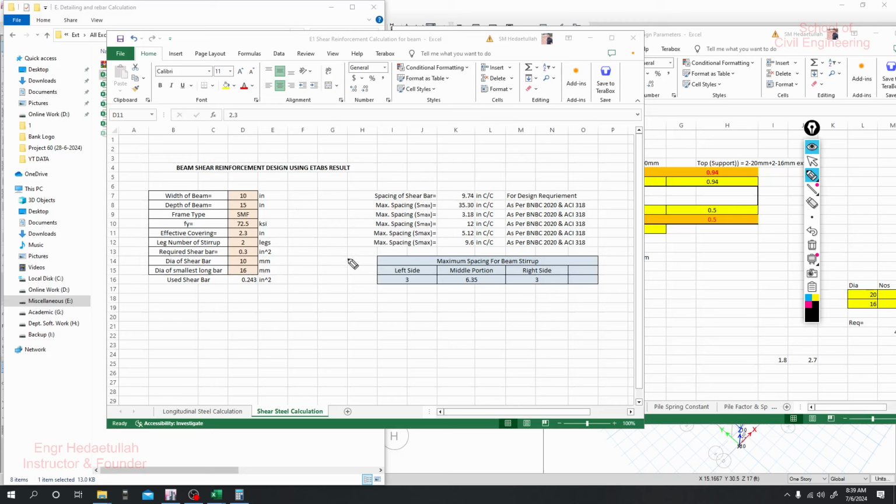When we have a long reinforcement here, clear cover means the covering after our stirrup, but effective covering is from the clear face of our concrete to the center of our long reinforcement. Is it clear? Normally in our country we provide 1.5 inch as a clear cover.